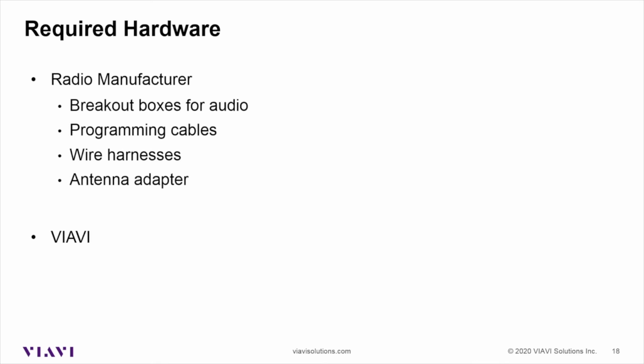Antenna adapters: I don't know if I would say most, but a lot of radios will use a mini UHF connector on the back of their mobiles. I know Motorola anyway has started to use QMA adapters on some of theirs, but there's a lot of different adapters out there, and some of them are radio model or radio manufacturer specific.